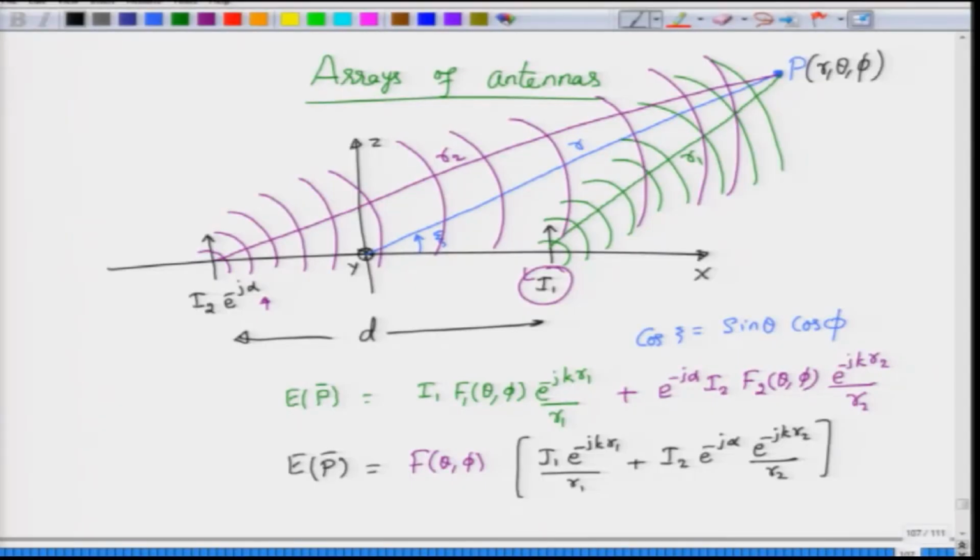Okay. So, if you actually take a compass and a pencil and do this carefully, you can obtain the antenna patterns, with a lot of work of course, by using this geometric sketch. And you can do it for any type of antenna array. This is something one can analyze mathematically, but if you place some other antennas randomly, then instead of working out the expressions, you can just pick up pencil, paper, compass and rulers, and work out the signal level at different points as you vary the observation point.